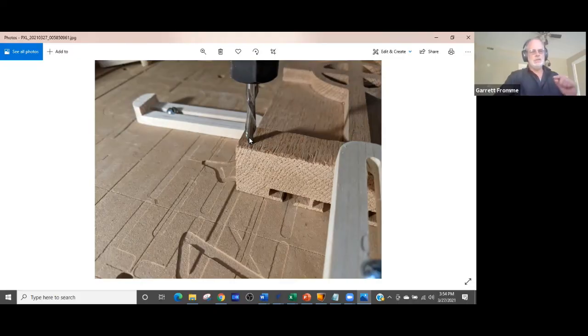And my G code says go up a full inch. I'm going to get an alarm because the software knows it can't go any further than 1/2 inch. So you're getting the alarm because your Z is not set right based on the motions the machine has to make, and you're trying to go too far beyond what the machine is capable of doing.